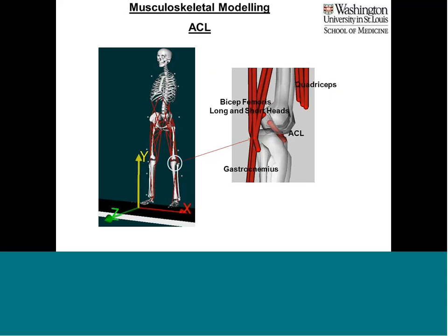I modeled more or less every subject on an individual basis, because if you do not place the ACL in the right orientation, then you run into the problem of it popping out during simulation, which you don't want. So individual care in modeling the ACL is an important step to getting successful results.